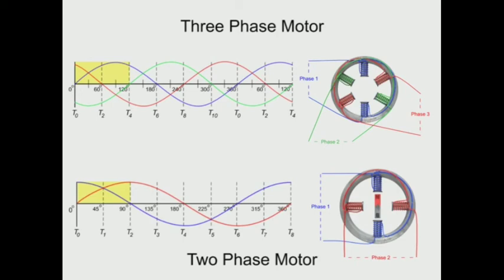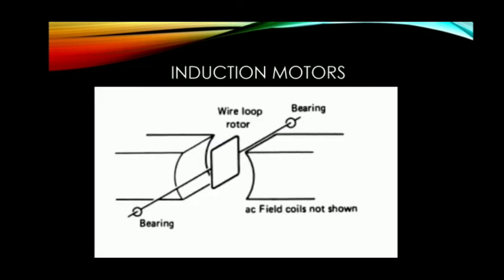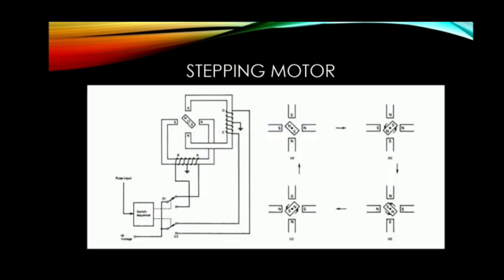Most common stepper motor does not use a PM, but rather a rotor of magnetic material, not a magnet, with a certain number of teeth. This rotor is driven by a phased arrangement of coils with a different number of poles so that the rotor can never be in perfect alignment with the stator. The direction of rotation of stepper motors can be changed just by changing the order in which different poles are activated and deactivated.